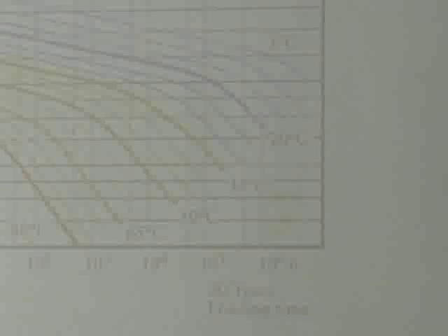That was just to talk about how we go to do a 50-year life based on maybe 6 months of test data. And the idea is to vary the temperature and vary the stress level. But you have to be careful because we see that transition between a certain failure mode that has this slope to another failure mode that has a different slope. And therefore, if we were to just test here and try to extrapolate, we'd be missing the right failure mode. And that's something to keep in mind in general with any accelerated testing.